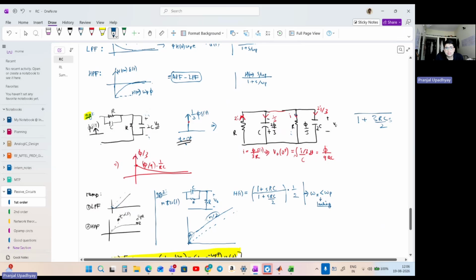And does this circuit have a zero? So again, one way that we discussed to check whether the circuit will have a zero or not is that imagine this is Z2, this is Z1, so Z2 plus Z1 is the transfer function. So the only thing now that we need to check for is that will Z2 go to zero when Z1 has not gone to zero? Yes, it will go to zero at this frequency,